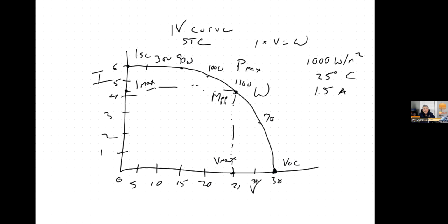Right? So these are the 5 places on the IV curve that the solar panel manufacturer is going to give you. And they're important for you to understand what they are. The MPP, the maximum power point, that's just under standard test conditions. Ideally, that's the most power that thing can produce. And if you're referring to it as a 400 watt panel, it's 400 watts at the maximum power point under standard test conditions. So that's what they're referring to. Everything's perfect and it's under standard test conditions.